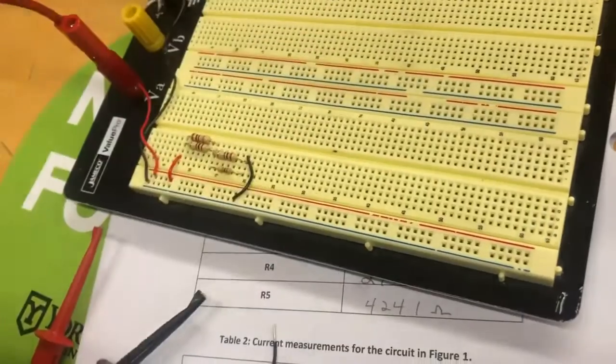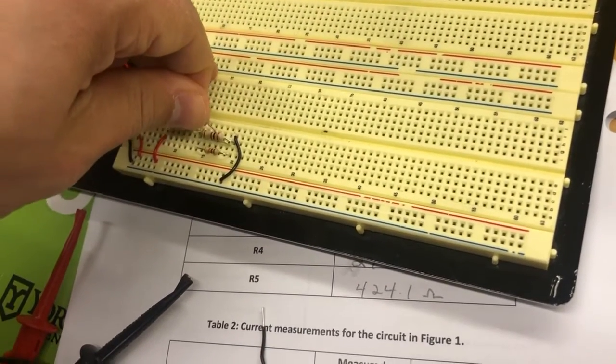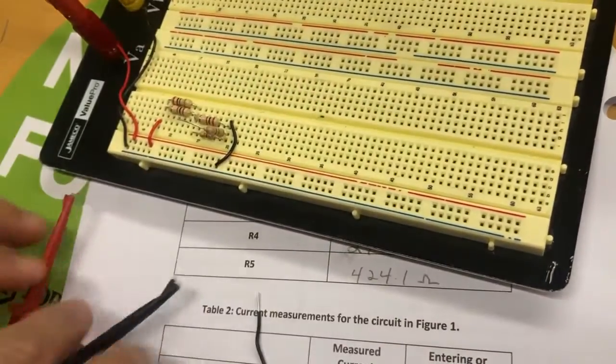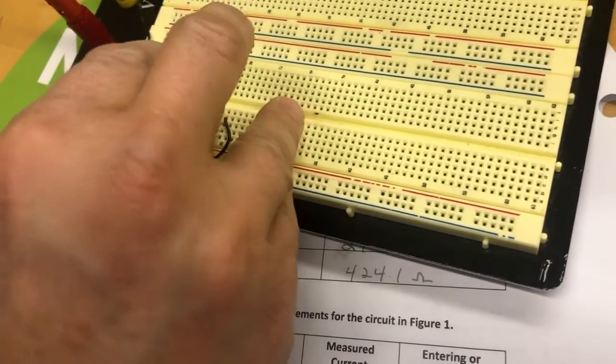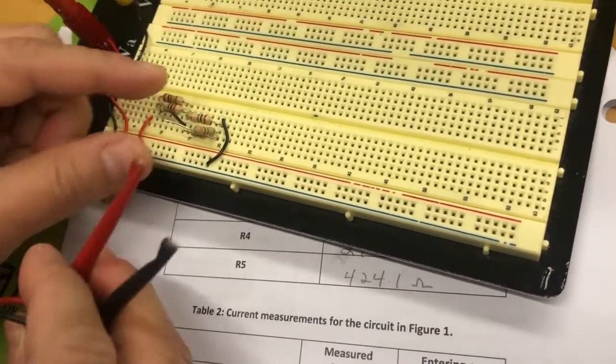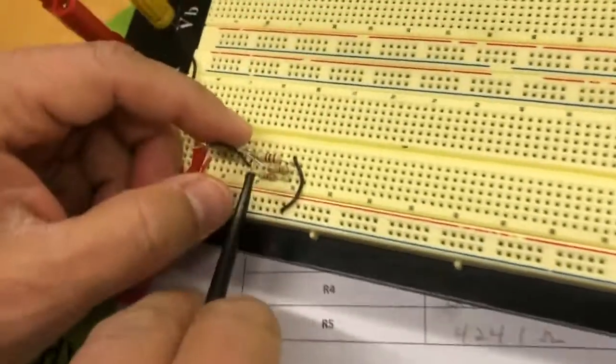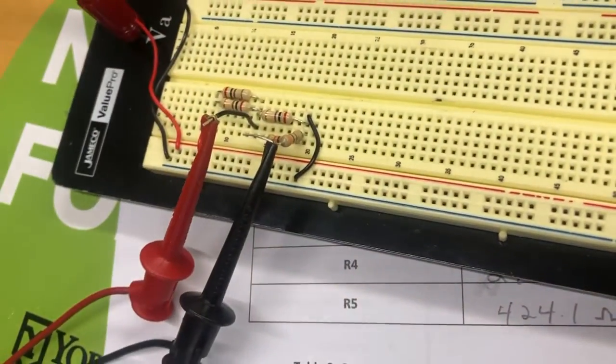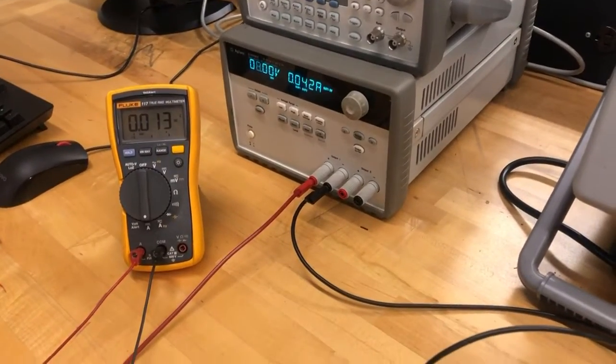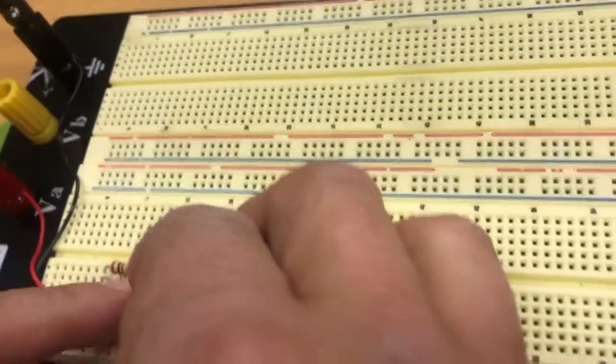So this next one on this side is connected, and this side is open here. So again, I'm gonna make this connection by using the meter. So meter incoming current coming here, outgoing going there, right? Then turn on the power supply. Now I'm getting 13 milliamps right there. This is I4, right? Then turn off the power supply, build the circuit back.